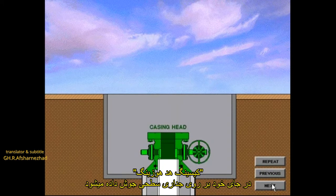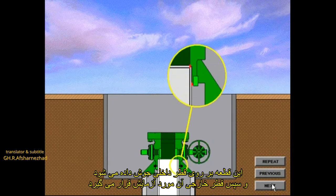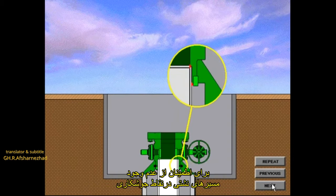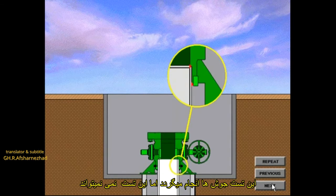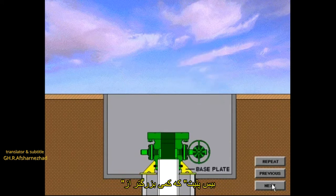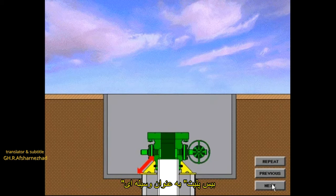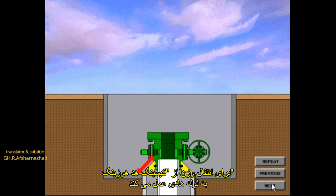The casing head housing is welded in place on the surface casing. The piece is welded on the inside diameter and the outside diameter, then tested to assure there are no leak paths in the welds. This test checks the welds but does not test the integrity of the casing head housing. The base plate, which is slightly larger than the conductor pipe, may be tack welded to the conductor pipe if desired. The base plate serves as a means to transfer weight from the casing head housing back onto the conductor pipe.